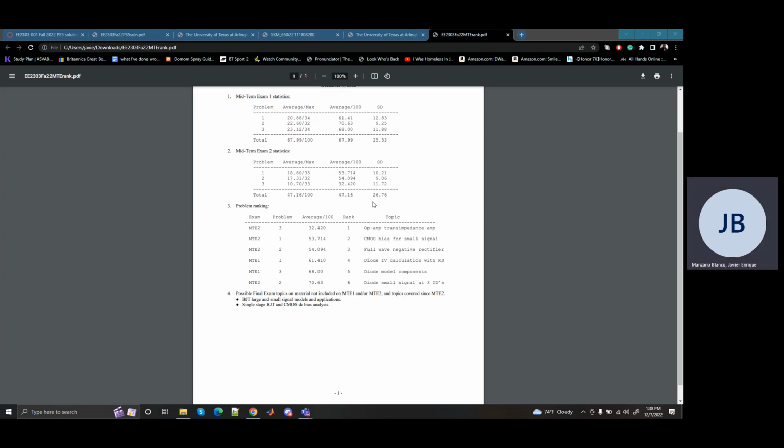The DC case, which gives me the bias, which sets me at VDD over 2, is set by the circuit where I treat these capacitors as open. What that looks like is just this guy right there, which is what problem set 5 has been about, which is what likely the exam question will be about: the analysis of the bias, not necessarily the analysis of the amplifier. If we want to analyze the amplifier,